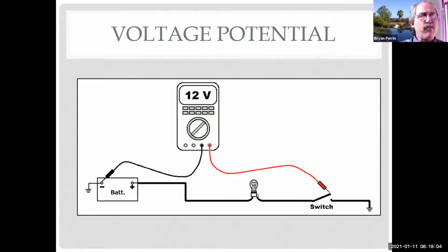So another way of looking at this is that if I have a water system and I have a valve that leaks, so I put a cap on it. Over time, even with a real slow valve leak, the pressure is going to be the same on both sides of the valve because there's a cap here. The cap is now providing the stop, right? So even though the valve might be closed or it might be open, it doesn't matter. I'm going to have the same pressure either side of the valve.